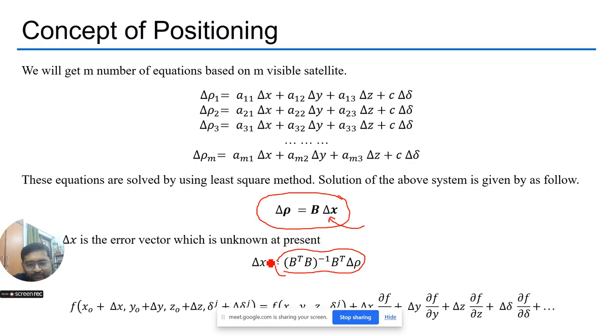There were four terms in the last lecture, when the sir was talking about different errors. There is a satellite geometry. How we can keep this satellite geometry so we get precise positioning? Those GDOP, PDOP, all came from these equations only. I will show you how we can get the formulas for that as well.